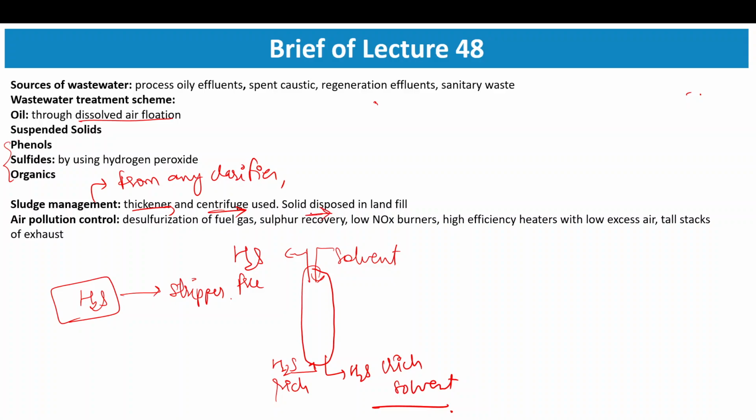Now, if we talk about this plant, it also generates a high amount of air pollution, because there is high sulfur content in the crude oil. During desulfurization of the crude oil and flue gas, the H2S which is formed may not all be recovered, and during sulfur recovery, H2S escapes into the atmosphere in the form of H2S or SOx.